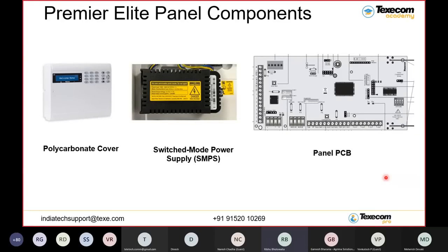The expanders should be connected to the control panel, and all the sensors should be enrolled first by putting everything on the table. I'm repeating: you have to do the programming of all the wireless sensors in your panel and your expanders, one by one, with everything on the table itself.